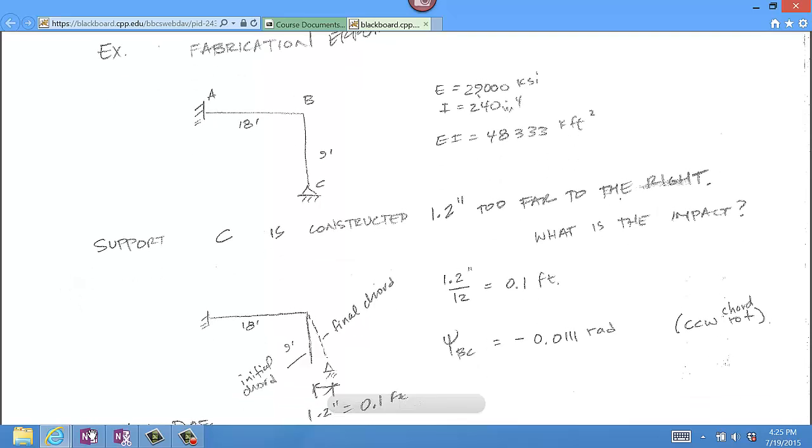And so looking at the slope deflection method specifically, the way to look at this is, again, you first try to identify any special case span. So do you see any? I see special case span BC and a general case span AB. So that means that you're going to be considering two general case equations, one for MAB, one for MBA, and one special case moment equation, which is M bar BC.